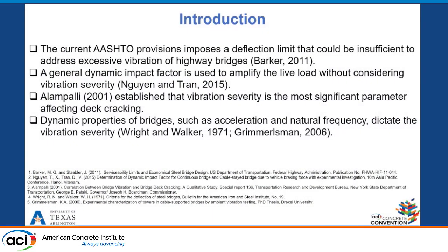The American Association of State Highway Officials, AASHTO 2020, only imposes a deflection limit that is insufficient to counteract vibration. In addition, a dynamic impact factor defined by the dynamic to static response ratio is used to amplify the live load without considering the vibration severity of the individual bridge.